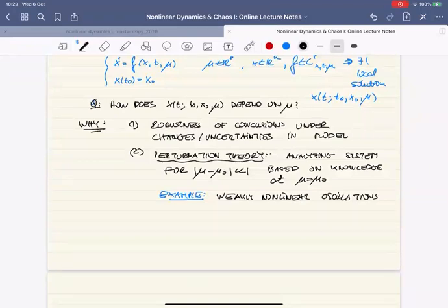So the generic form of such a system, just to simplify, in 1 degree of freedom, would be some mass times some displacement double dot, then you would have some linear damping, c x dot, plus k x. If you learn mechanics, some call this the MKC system, except that you may have matrices here when it's multidimensional.